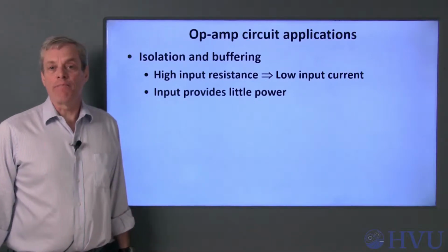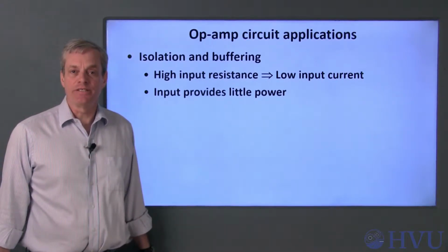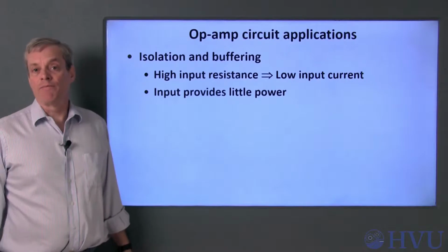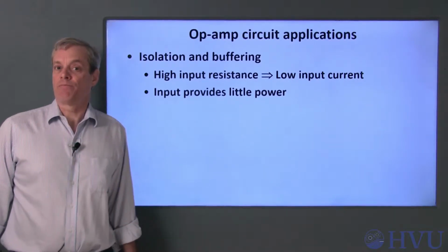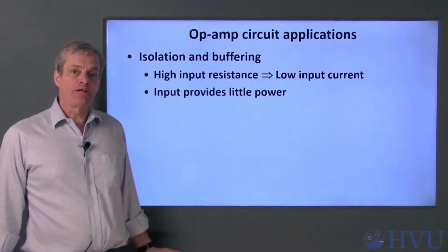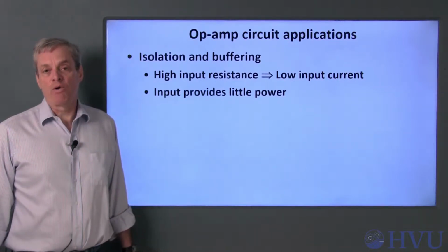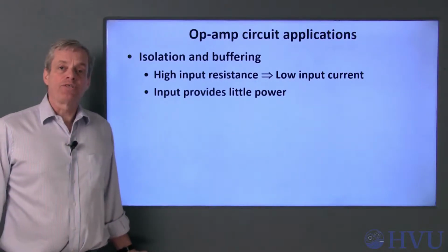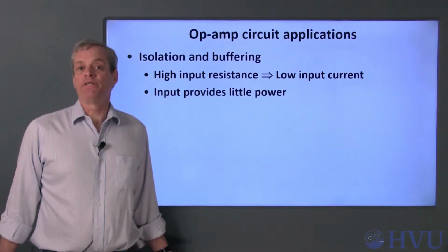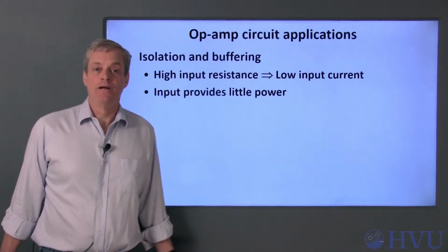A common example of this is in instrumentation systems, where some physical parameter is being measured. In many cases, the sensors used to measure the parameter may produce the necessary voltage, but they don't have the power necessary to transmit or record the signal. Op-amp circuits are a common choice to increase the power output from a sensor.